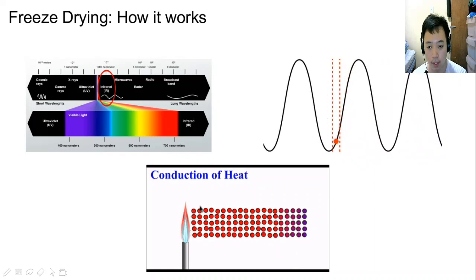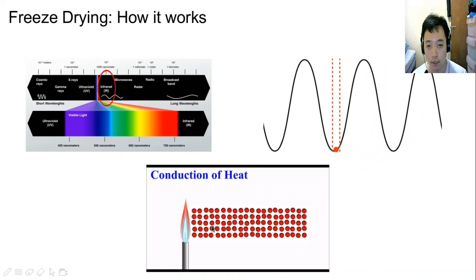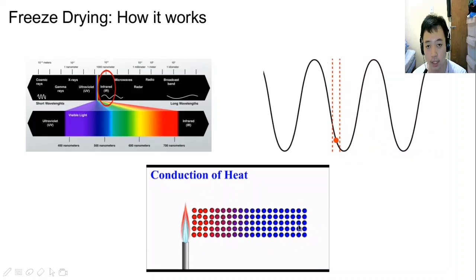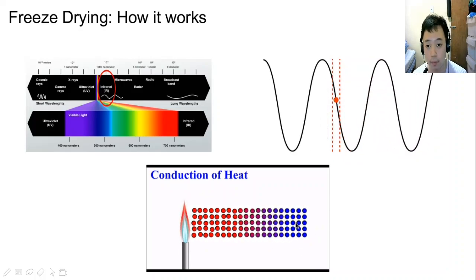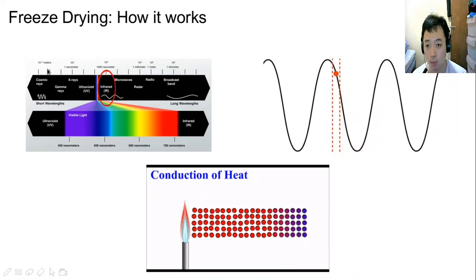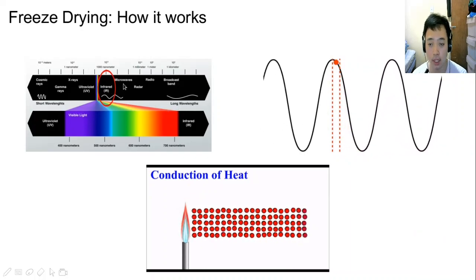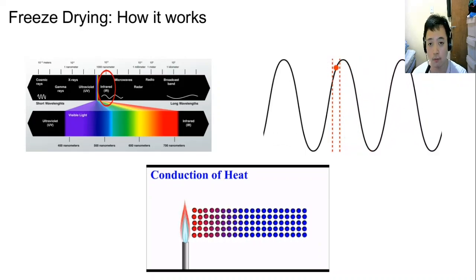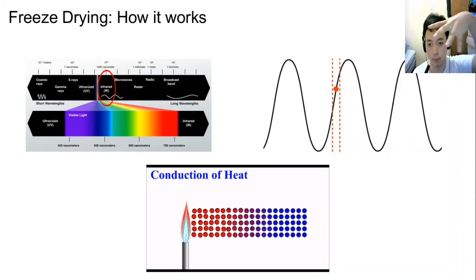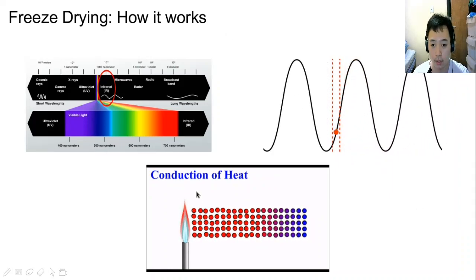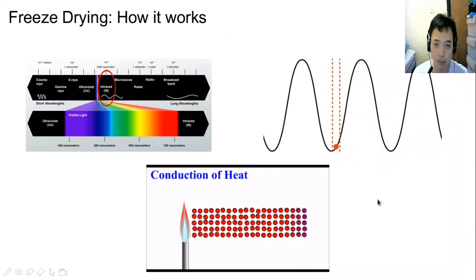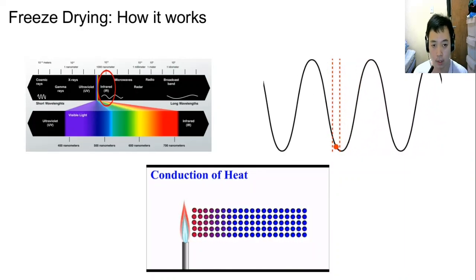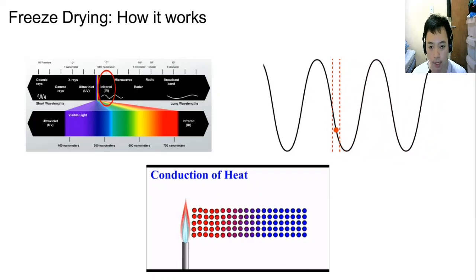You see, this part will be heated first, and the products on this side are still cold. Same with infrared. But in infrared, it works in products that don't have an even surface, since it's just a beam of radiation. In conduction, the product has to be relatively flat for it to be effective, so that it can conduct heat in a higher surface area.